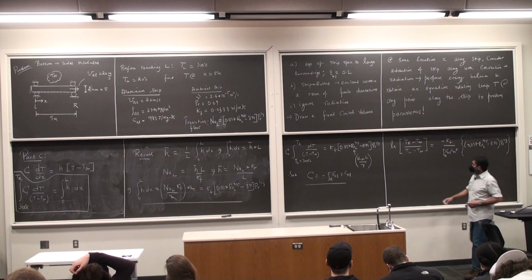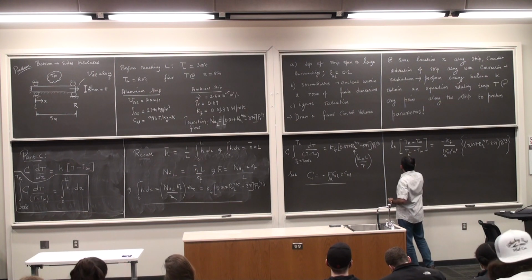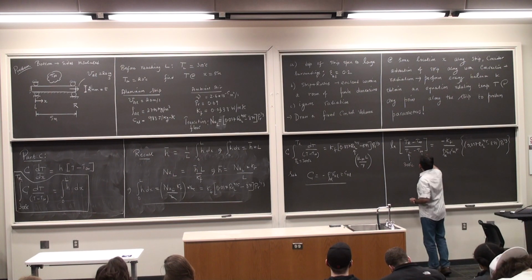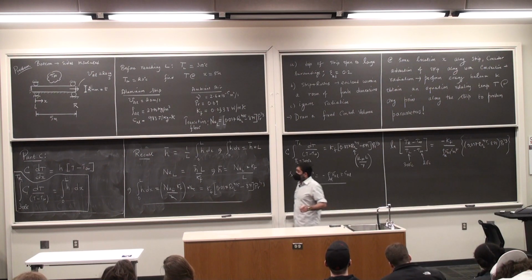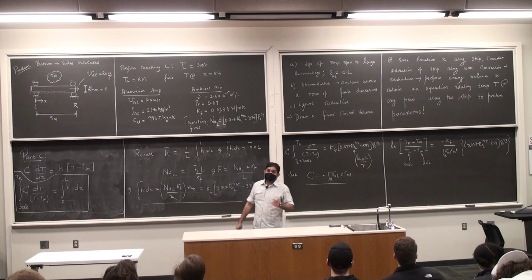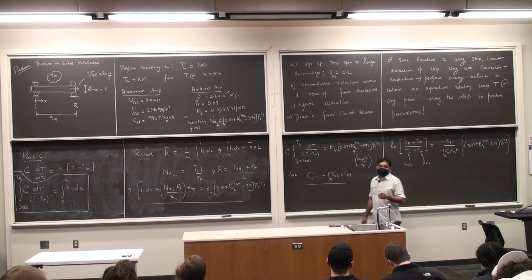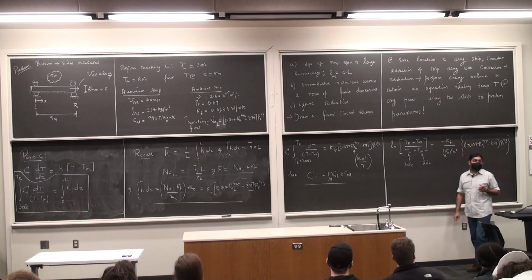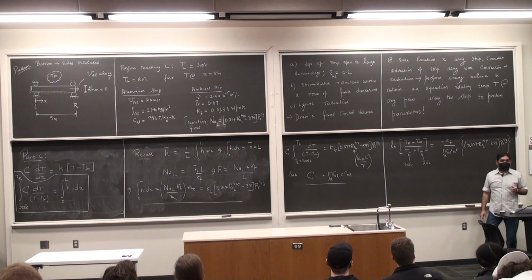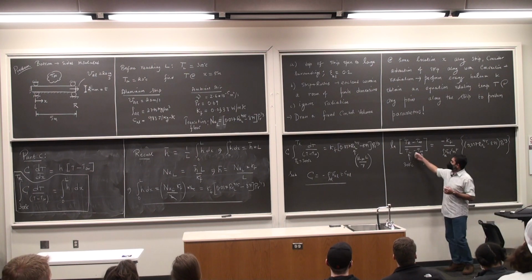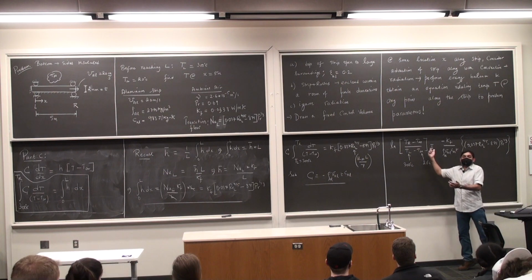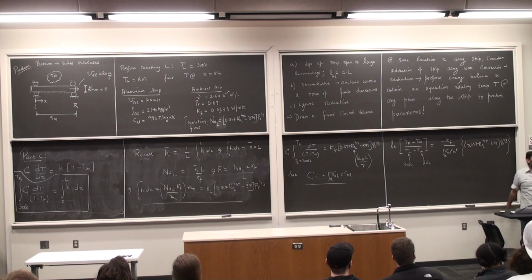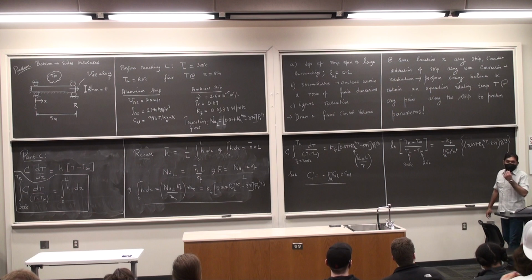Substitute. TL was 300 degrees Celsius. This was 20 degrees Celsius. Be careful, if I told you that radiation was a part of the mixture, what should you do for your temperatures? You should put them in Kelvin. Please be careful. Here it does not make a huge difference because these are temperature differences, but you obviously will not be ending up with this kind of a neat solution if you brought in radiation into the mix. That's a nonlinear differential equation. You'll have to solve it numerically.